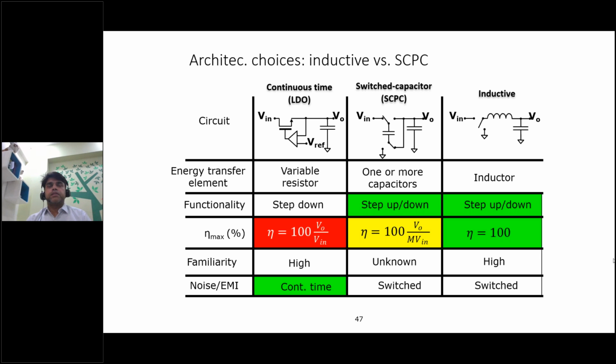its advantage is that it is one of the lowest noise solutions, but it has limitations: it can only convert from, let's say, 3 volt to 1.8 volt, or 1.8 volt to 0.9 volt, a step down. It can only generate a voltage which is lower than the battery supply, the source. And while doing that, it's not even energy efficient.